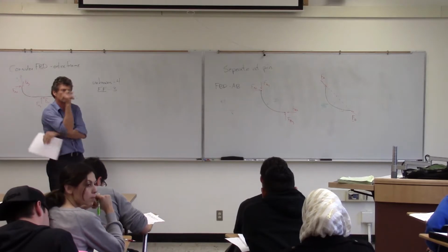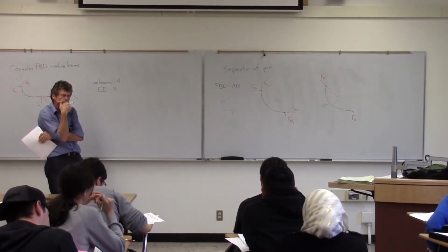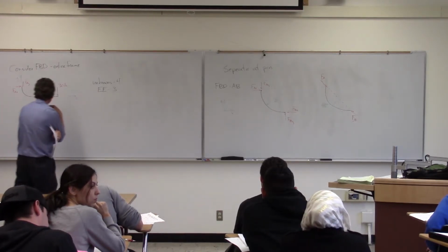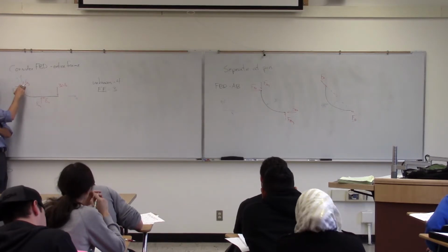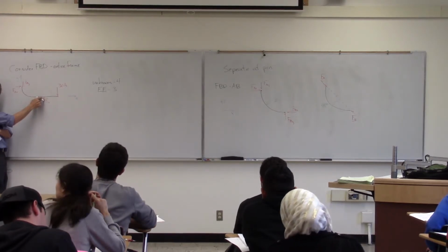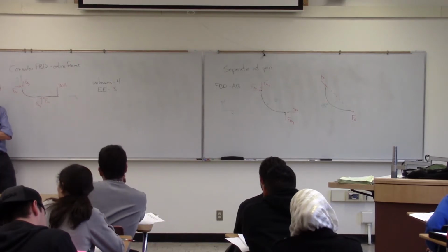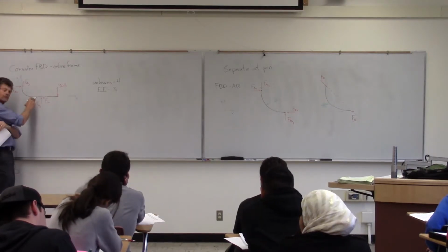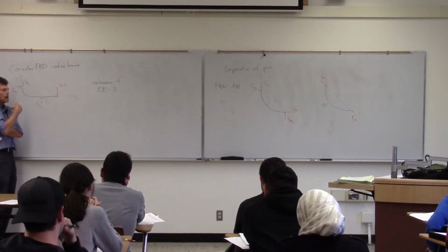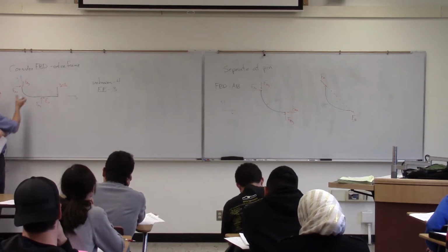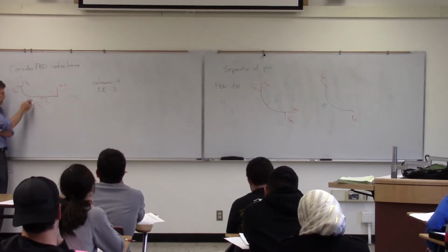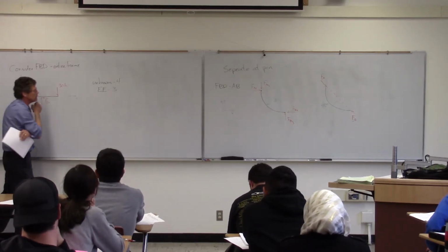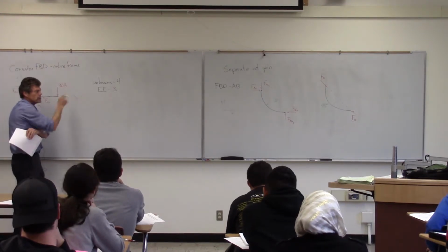So since forces A and C are mounted at 30 pounds as an applied force, is that why those are the only ones on the original free body diagram, because they're external? This is external. I pulled the ground away from this one, right? I pulled the ground away from this one, and then the 30 is existing there. That make sense? So that's a really, really good point, because a lot of people start seeing forces showing up here in the middle there, and boy, it messes up the equilibrium equations in a hurry. Only what's external going on here. So I'm pulling that away. I've not pulled B away from the structure. B is part of that structure there, so it's not doing anything. It's doing work in here, but we don't see it in terms of its forces.